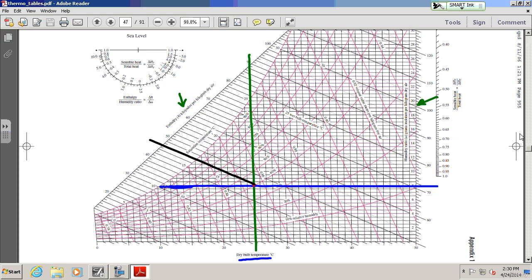What we used to do is have two thermometers. You had one thermometer, what was called the dry bulb. It was just a standard thermometer like you've seen your whole life, that you probably used as a kid, stuck in your mouth when you had a fever. The other thermometer was also a normal thermometer, but we put it inside a wick that had some water on it. The wick would be some material that would enable you to absorb some water. And essentially what would happen is the water would evaporate when you spun it around.